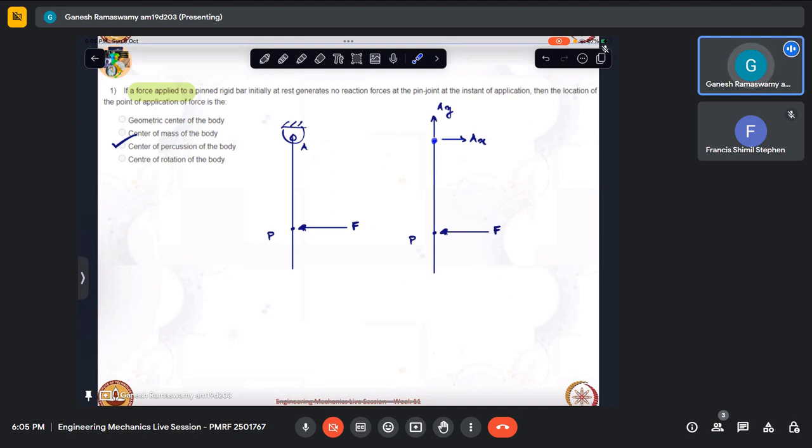If I allow that rotation, let us say this is the initial configuration, then at the next instant the configuration would have to be this, right? Because of that rotation, if it were allowed. But this movement is not allowed. So the pin would apply a reaction like that in order to counter that rotation.